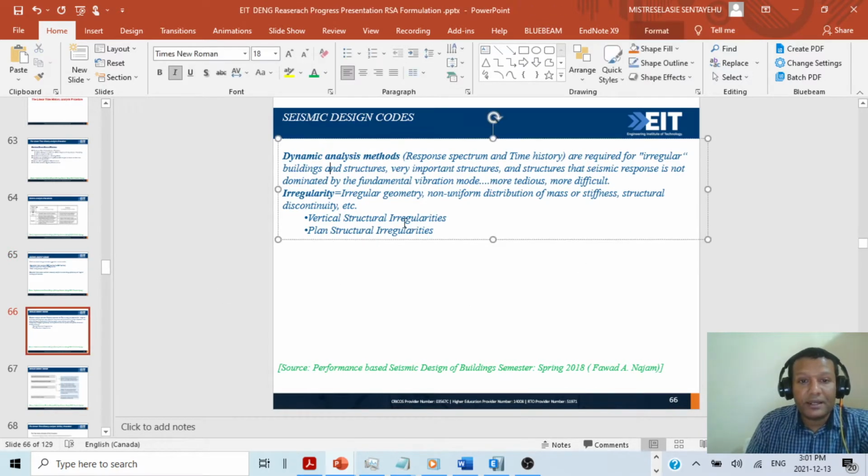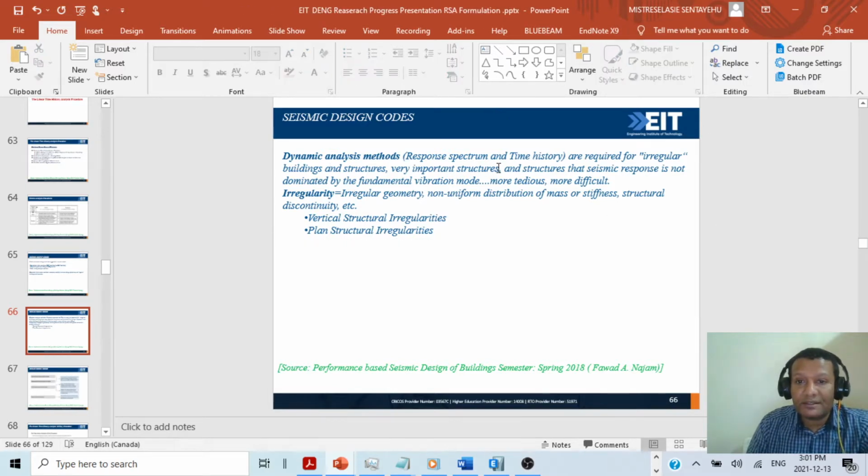Let's continue. Dynamic analysis methods, response spectrum and time history analysis, are required for irregular buildings and structures, very important structures, and structures in which the seismic response is not dominated by the fundamental vibration mode.